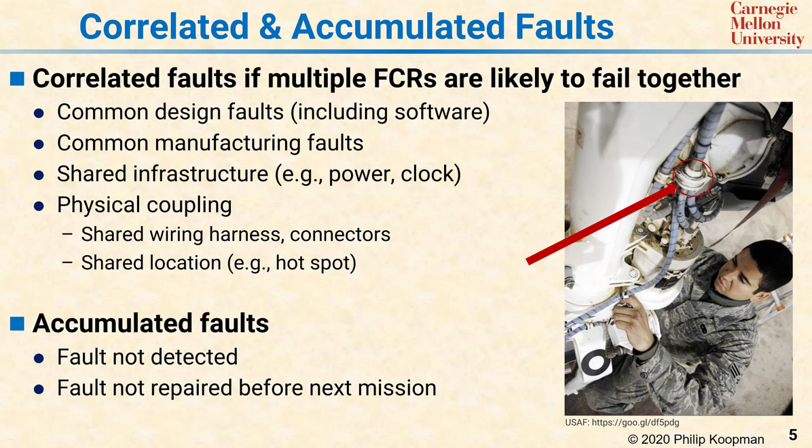As a very simple example, consider that commercial airliners have 2 engines or more. The safety case is basically, if you have 2 engines when you take off, even if one dies, you have a second one that you can use to land. But that reasoning doesn't work if on the previous flight one of the 2 engines failed and you didn't fix it before the next takeoff. It is essential to detect and repair faults in a timely manner and to take into account the possibility that you have faulty units during a mission when you do your redundancy calculations.